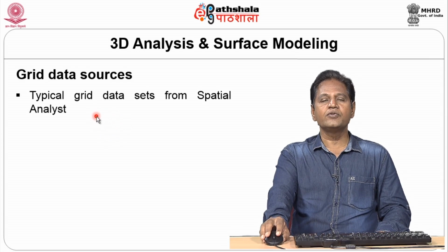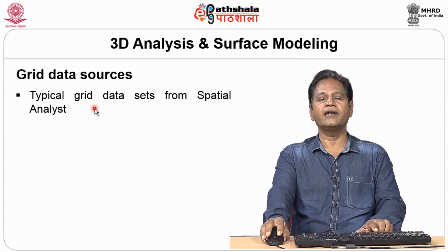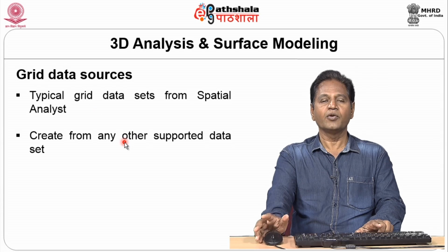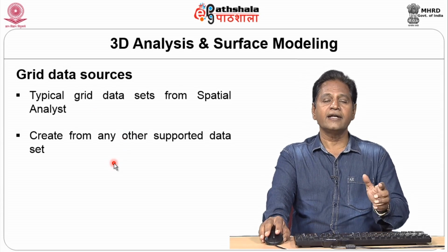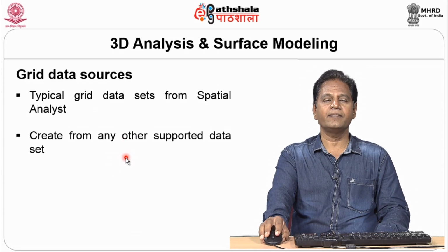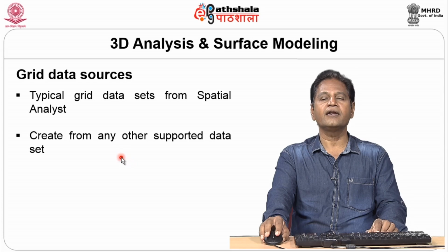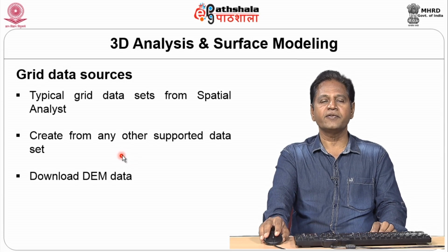So, what do we use? Use your Spatial Analyst, one of the extensions of your ArcGIS software, convert the data into grid data and utilize that. That could be one of the resources. Or any other data which is supported; it does not necessarily need to be in a specific software or a specific extension. It could be any other software, any other data source. You have Vertical Mapper in your MapInfo, things like that. So, that sort of thing can be used.